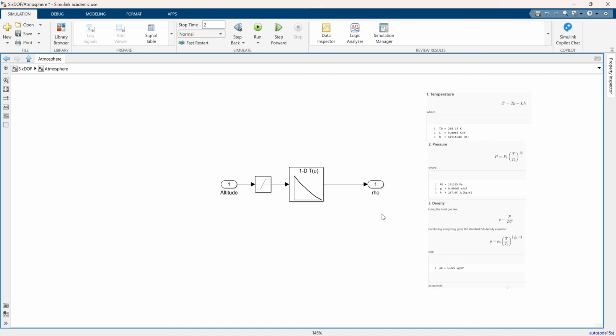However, imagine, lookup tables are used from, like I said, real flight data. And when that is the case, not for this specific Q bar calculation, but for other stability derivatives, control derivatives, things like that, there is only flight data. If you do the formula way, it can only get you so far. But the real flight data is what you want to emulate, which is why there is no option of doing formulas there. You want to learn how to do lookup tables there. So that is why I use this to give you a little glimpse of how it is used.